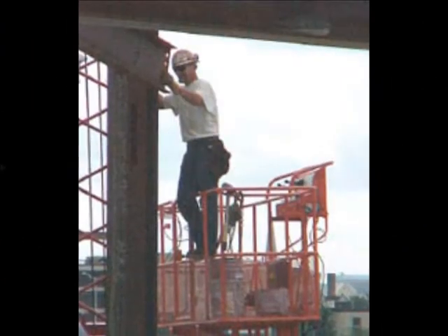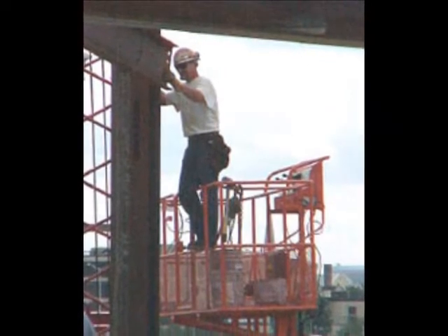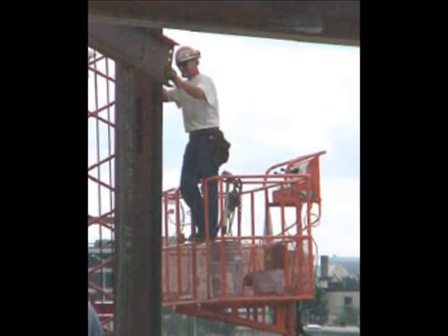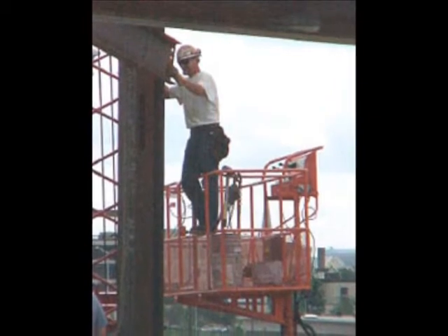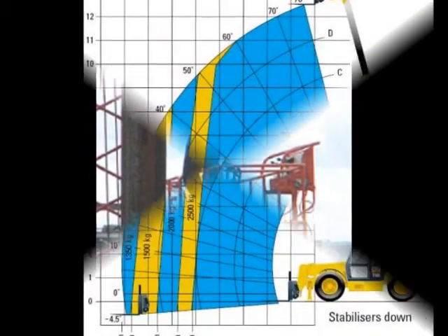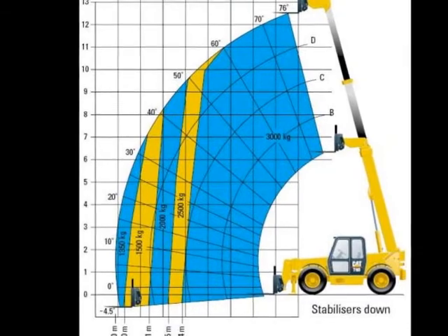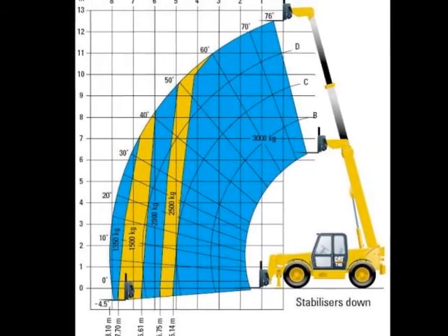While using a man lift, employees shall stand firmly on the floor of the basket, never sitting or standing on the edge of the basket. Also, boom and basket loads are specified by manufacturers, and these loads shall never be exceeded.